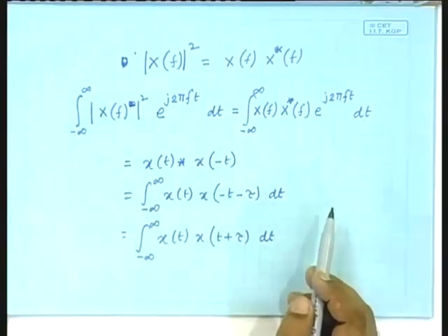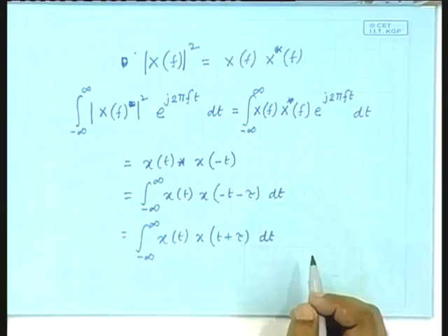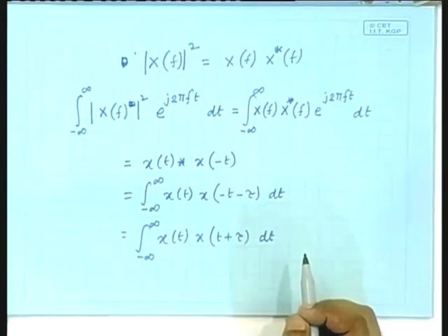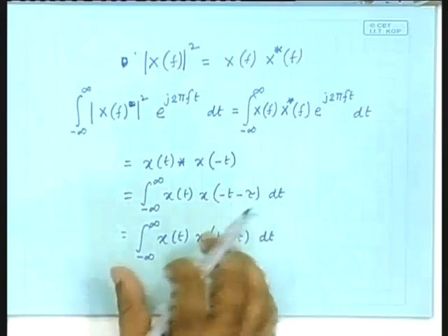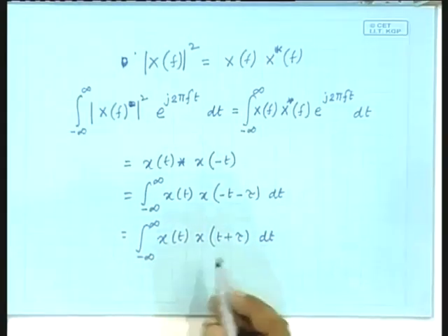No, actually it will not be. The issue is that different books give different definitions of this function, and in some cases they take the t as a variable, in some cases they take the tau. Yes, sir, but the LHS is a function of t, and the RHS is not integrating over t, so it will be a function of tau. LHS is a function of t, x(t) convolved with x(minus t). And the RHS is integrated over t, so ultimately it is a function of tau. Oh, so you have to interchange these two, t and tau. You might as well interchange these two to bring in this form. So essentially, it is the same thing. It will not be different if you interchange t and tau.